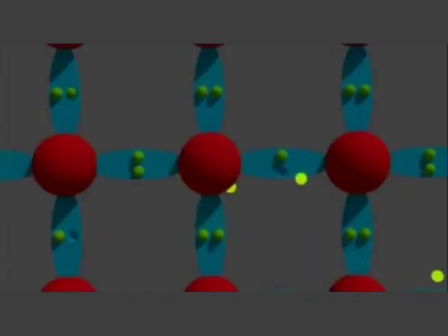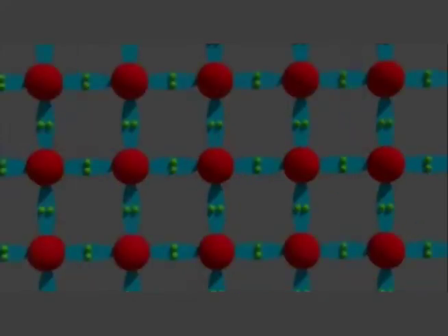Because electrons are dislodged by heat energy, more electron-hole pairs are formed as heat energy is increased. This explains why semiconductors conduct better at high temperatures, due to the generation of more mobile charge carriers, electrons and holes. Also, notice that the atoms are fixed in the crystal lattice and do not move.